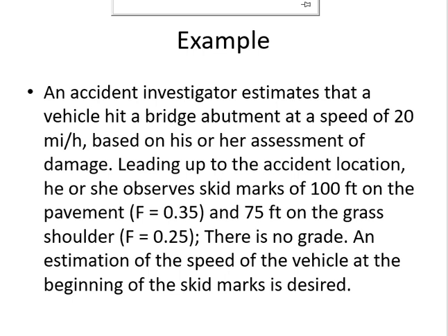We are doing the topic of components of traffic system, and there are 5 components: road users, vehicles, streets and highways, traffic control devices, and general environment. In road users, we discuss 2 main parties, the drivers and pedestrians. For drivers, the important characteristics are visual acuity, reaction process, and personality and psychology. For pedestrians, the important characteristic for design is their walking speed.